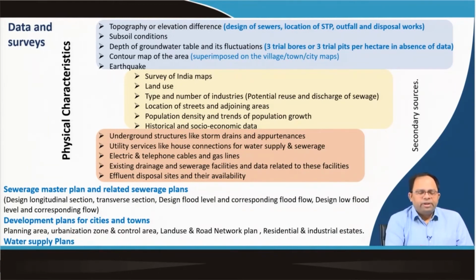We will require data on topography or elevation difference. This actually influences design of sewers, location of STP, outfall and disposal works. So, the entire network design is based on topography. When we talk about urban floods, we need to understand topography or the digital elevation model. So, this is very, very important.